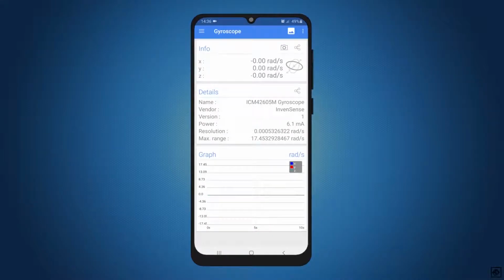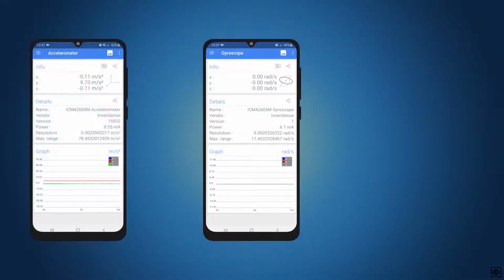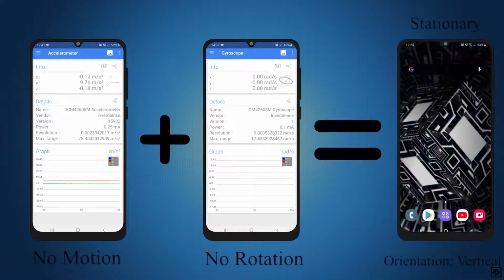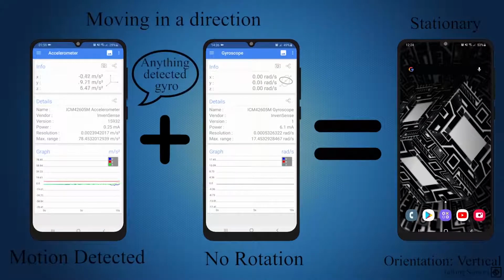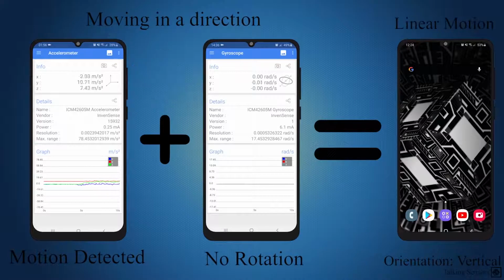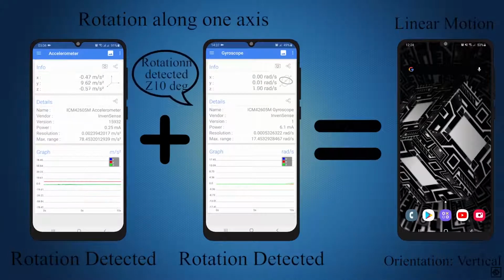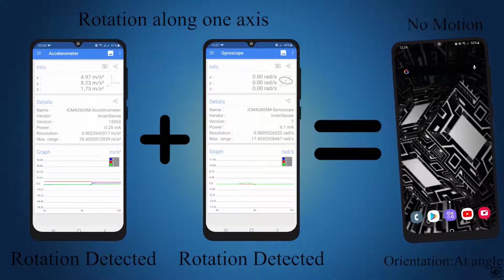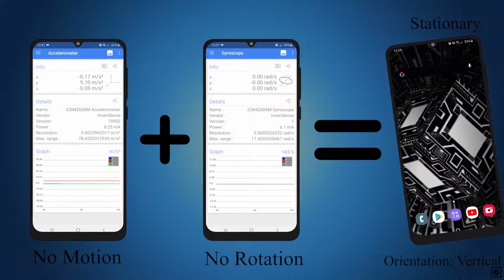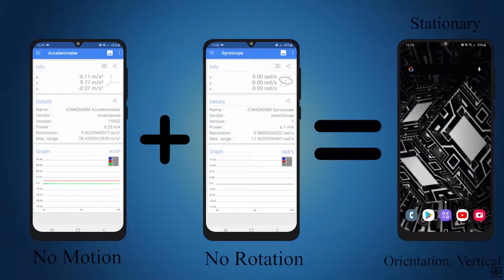Due to these uncertainties of accelerometer and gyroscopes, they apply a principle called sensor fusion, in which they combine data of different sensors to achieve a much more certain outcome. We know that when in motion the accelerometer will actually detect the perceived gravity, not the actual gravity or acceleration. By using the rotational information from the gyroscope, we can estimate what the actual gravity vector should be. Also, we can subtract it from the perceived gravity vector to calculate the true acceleration.